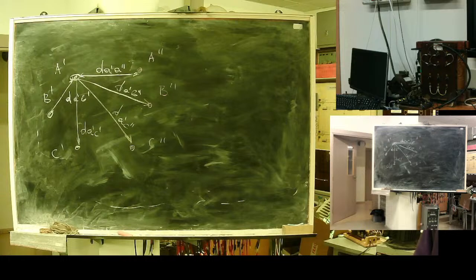If you are looking for really high precision calculus, for example, you're calculating losses and you need real precision within 1 in 1000, that means you're in trouble, because you will need to split the line into stages and calculate each stage in phase coordinates using the first formulas I started with.